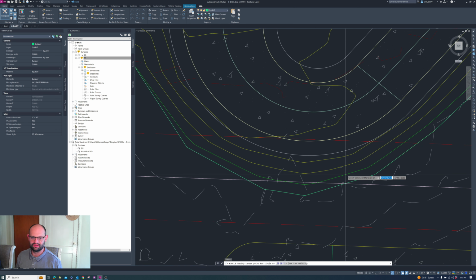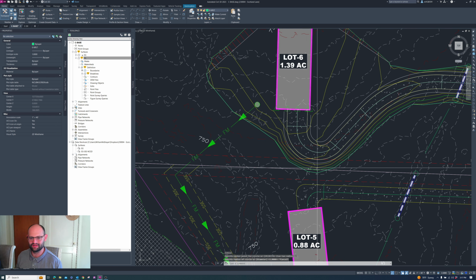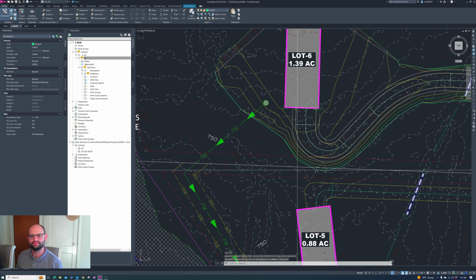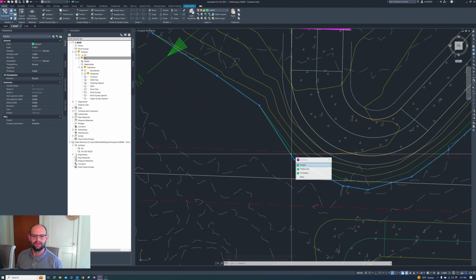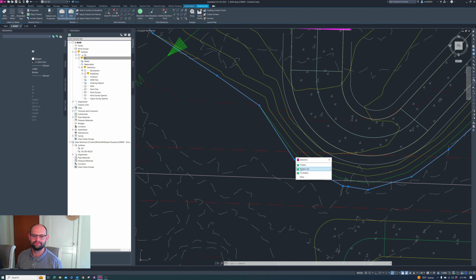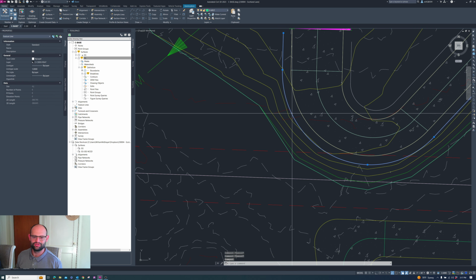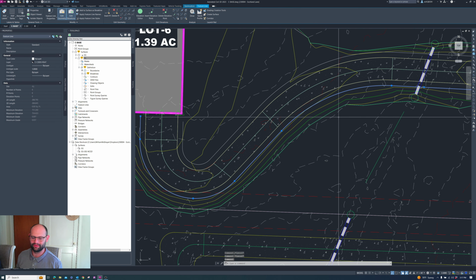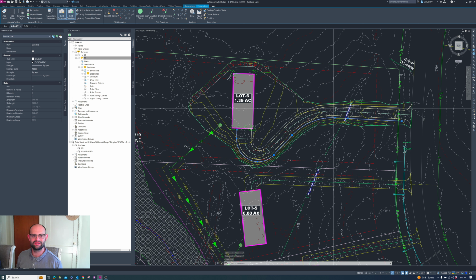Let's check the space between our contours. We're somewhere near 2:1 there. Let's get that fixed. Let's check it with a grading group to see where we really should land. I have that one selected. I'm going to bring back up the grading creation tools.